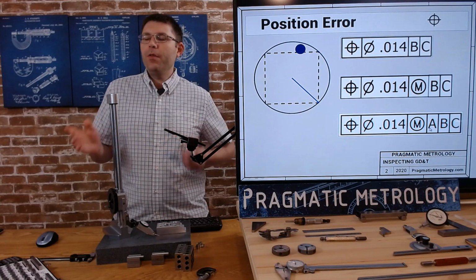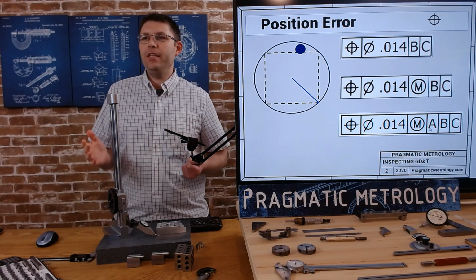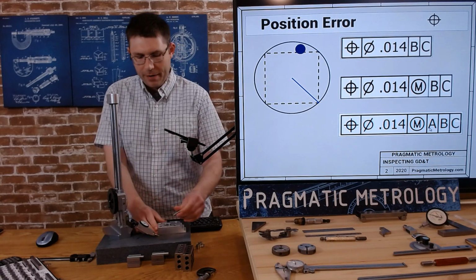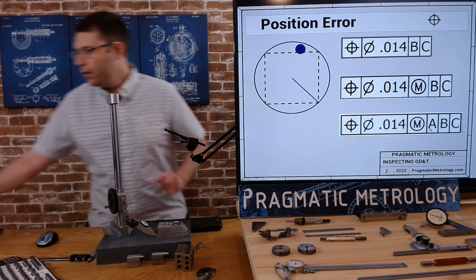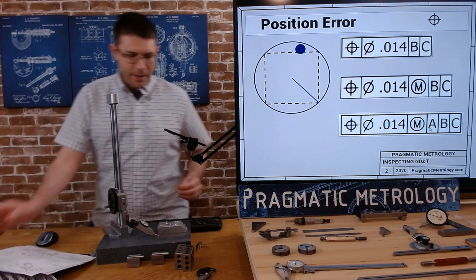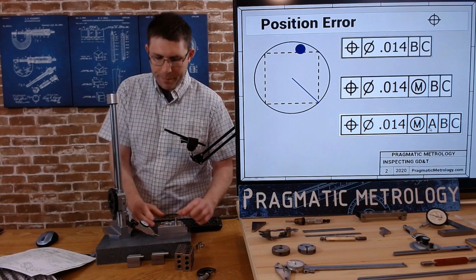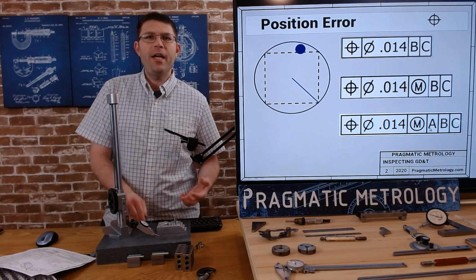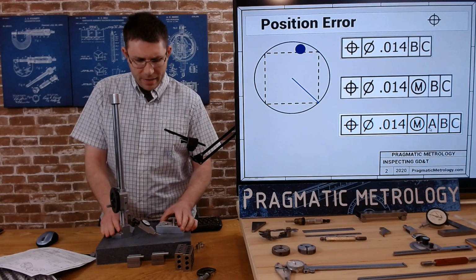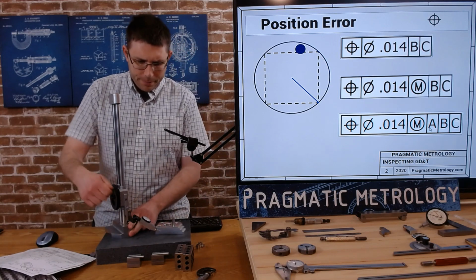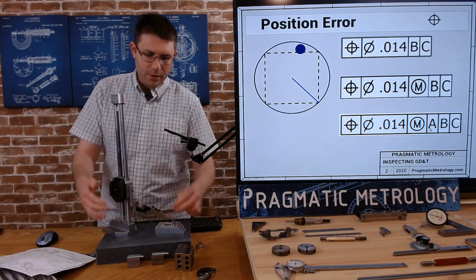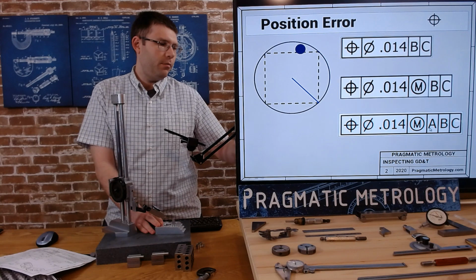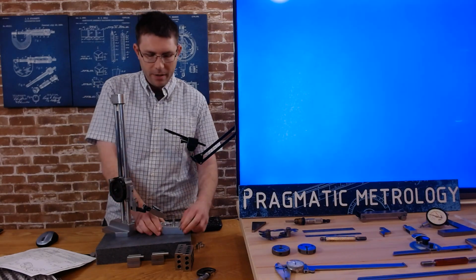So with my B and C datum, I have 14 thousandths. And if I add in A, I have to account for that as well. So how we're going to do that, once we measure datum B and datum C, I think it was about 9 thousandths from the video. I can't remember exactly. But we're going to measure how much out of perpendicular. Let me flip over to the second monitor.